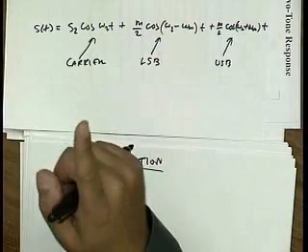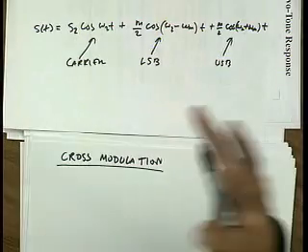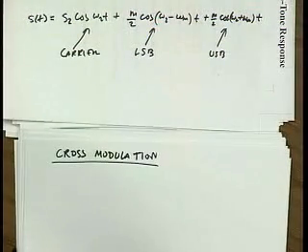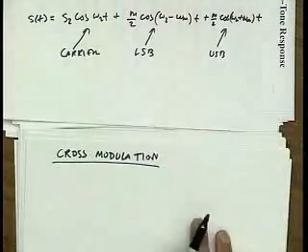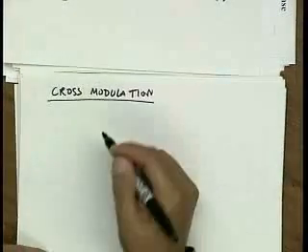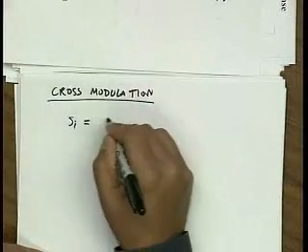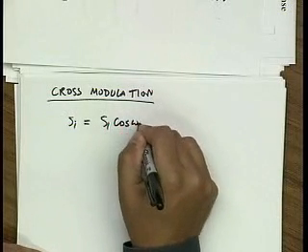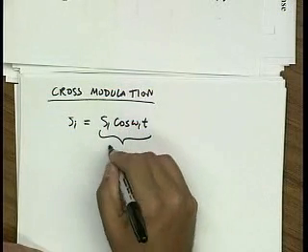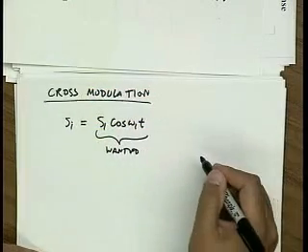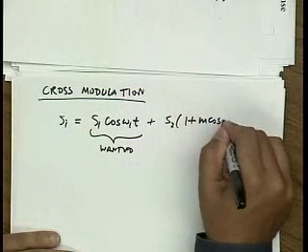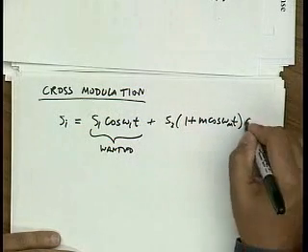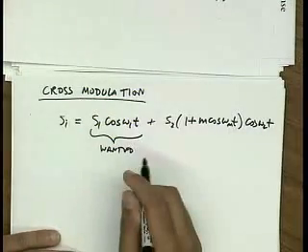So even if there were no modulation on another channel, all of a sudden the video, let's say, gets transferred to the other channel. Well, that's really annoying. You're watching your soccer game, and all of a sudden you see someone dancing in front of you. Even if it's faint, you only want to see soccer players. So what we're going to see is, let's say we have this wanted signal, and we assume it's blank, but somehow or another we're going to see a modulation, cosine omega 1, appear at the second frequency.